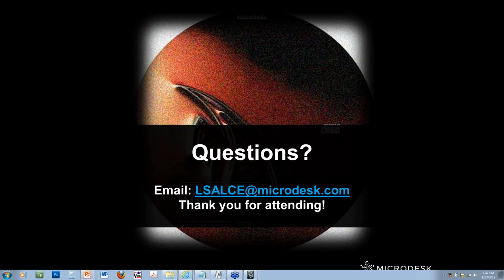Actually, the answer is yes, the short answer. Maya allows for what they call direct connect, DWG export, import. So although it may not open directly the file, just like most of their high-end visualizations, it allows you to export out of Revit into both formats, FBX, which is a more complete format and a better supporter in a more efficient workflow, and a DWG as well.